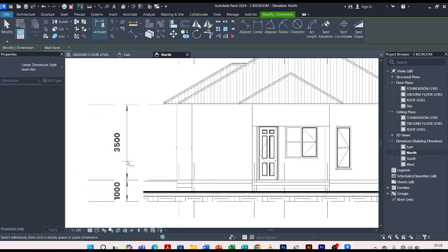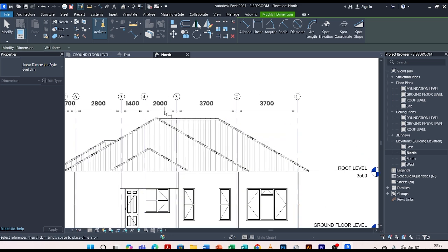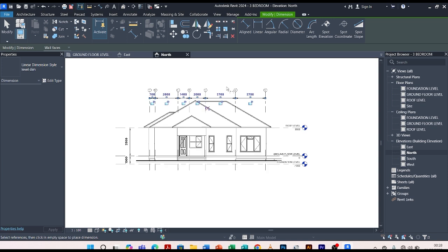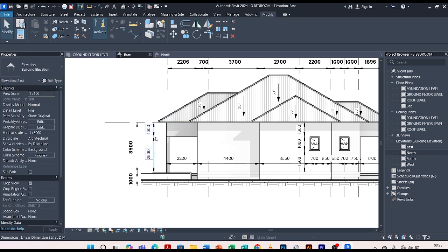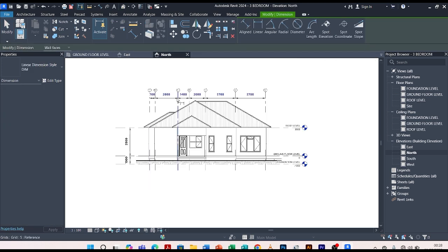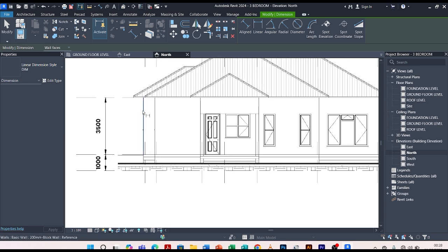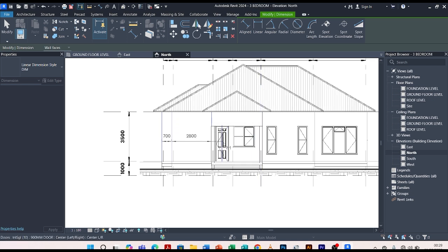So it has picked parameters of the other dimensioning line. So I'll do the same to this one, because we're having the same for the grid lines. Like that. Then I'll come back still on my elevation, that is the east elevation. I click on it. I'm going to create similar of this dimension line. So I click on it, I type CS on the keyboard, then I go to the next elevation. I'll mark off this, mark off this, mark off this.